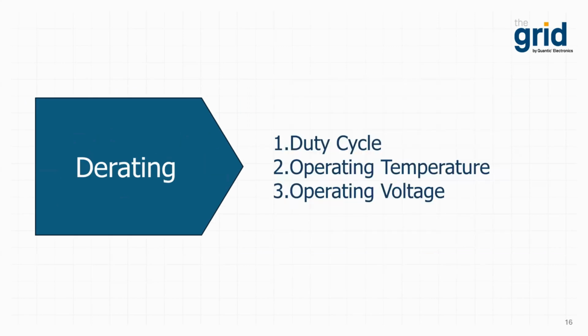The lifespan of the mission typically dictates the needed lifespan of the capacitor. Typical derate criteria are defined in various MIL standards. A 50 to 60% voltage derate is typical, but can vary depending on individual mission profiles. Primary factors that impact capacitor life include the capacitor's duty cycle, operating temperature, and operating voltage. The lower the operating voltage and temperature, the longer the capacitor will last.